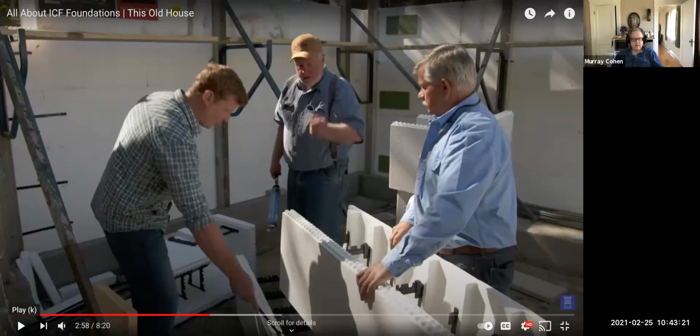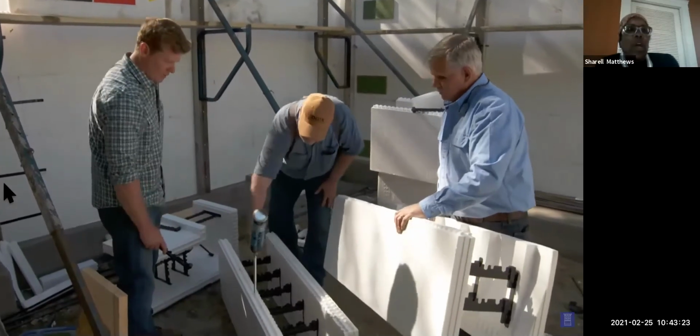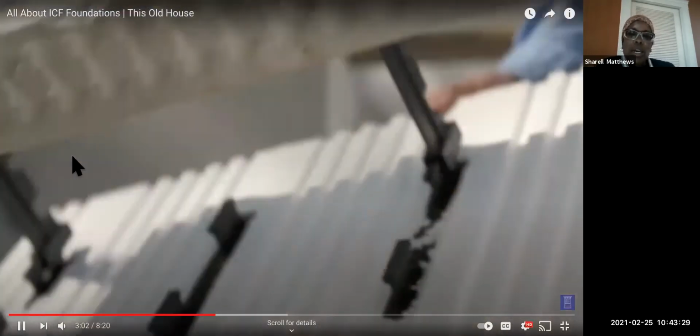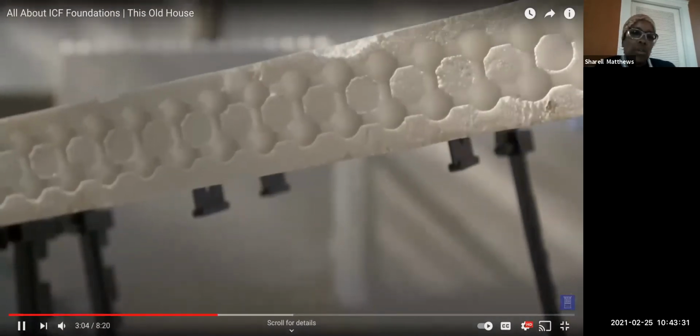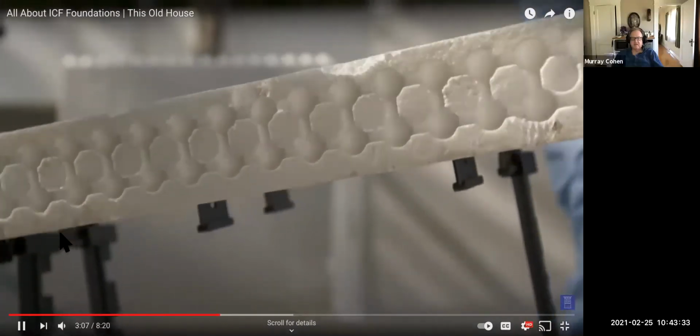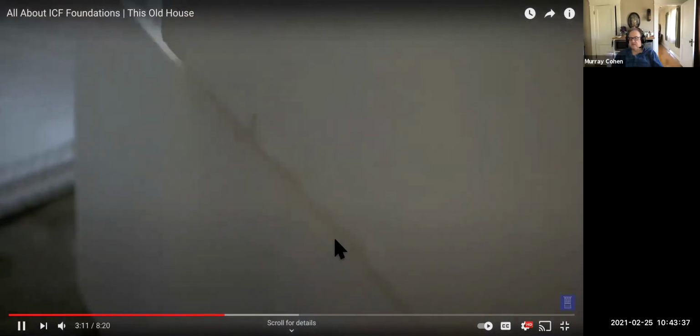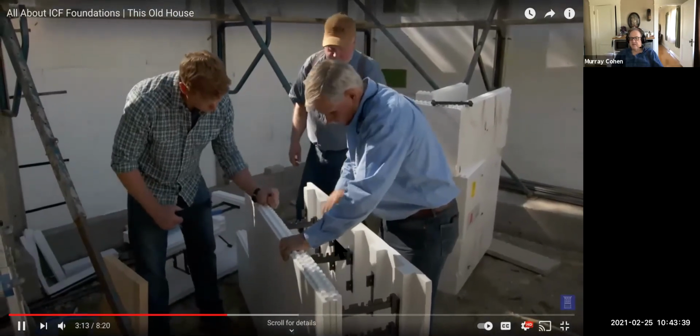Syed, you would know that. Right down here, I believe they do have those boards, like you see those boards around there. Those snap boards are keeping it together. If you look underneath, it's actually a male and a female joint. So when you push these panels together, they lock. This is what keeps it sealed. You want to make sure you line up these plastic ties right here.